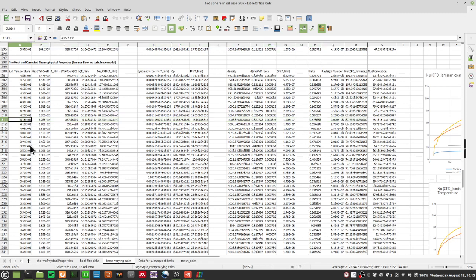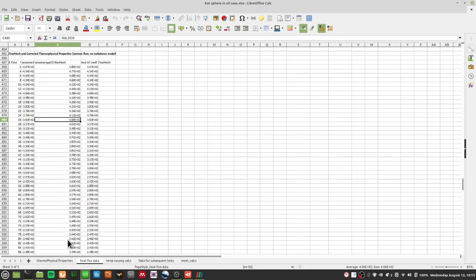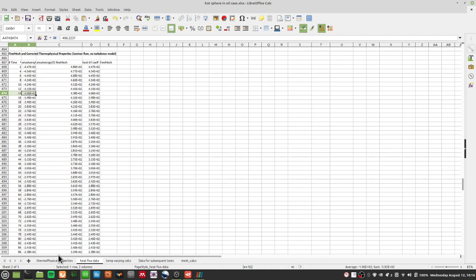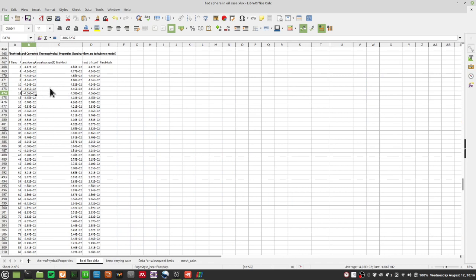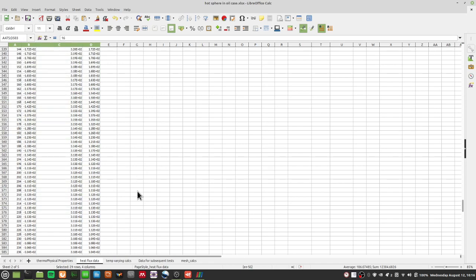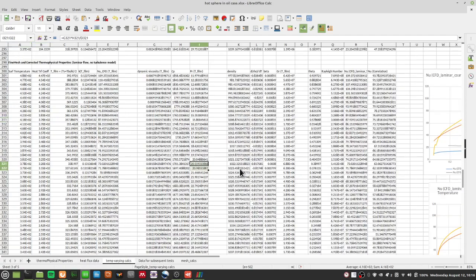This surface temperature is 416 Kelvin. So it's 500 Kelvin and 300 Kelvin. Average area temperature 416. Okay, it's around here. So in effect, the turbulence only lasts for the first 10 to 12 seconds. Everything else, you pass below into the laminar regime. So putting a turbulence model there doesn't really seem to make sense.